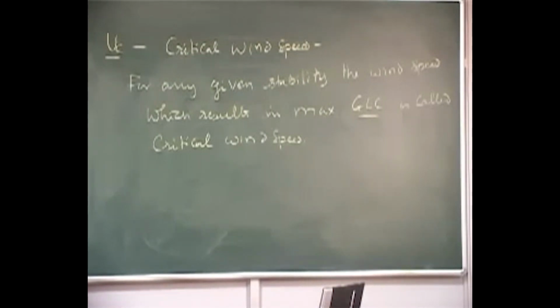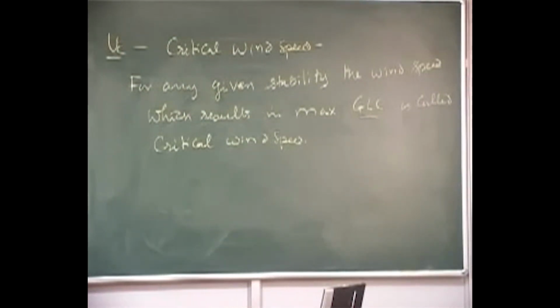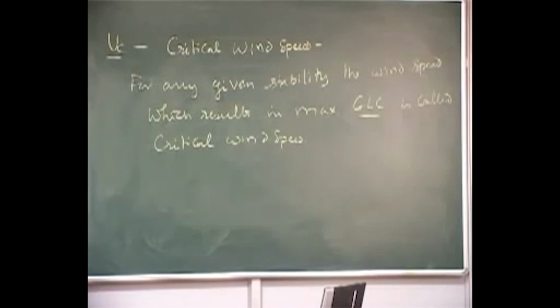So, what do we do? We are all the time interested in where the maximum concentration will occur. But what I do not know is that critical wind speed. Although there are many formulations that have been developed, where you can find out mathematically where the concentration will be, what you need to do is differentiate this one again with respect to wind speed, and find out this thing and put the formulation for the maximum concentration and things like that.